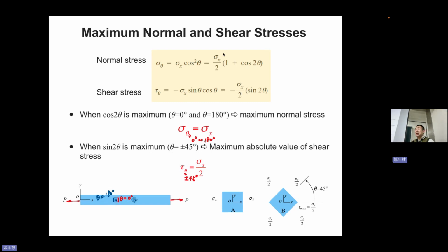This surface means theta equal to 0. Our focus for this one is theta equal to 0, but for that surface, our focus is now on this one, theta equal to 180 degree. Of course, this stress element has 4 surfaces. And you can substitute this as 90 degree, this as 270 degree, and you find that this is 0.